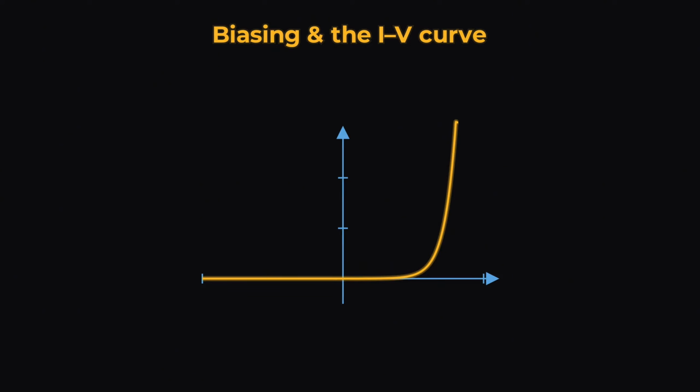One misconception must be corrected here. The diode conducts at all forward voltages, because the relationship is exponential. The value 0.7 volts is simply where the steep part lands on a linear plot. It is not a switch that turns on at a fixed point.